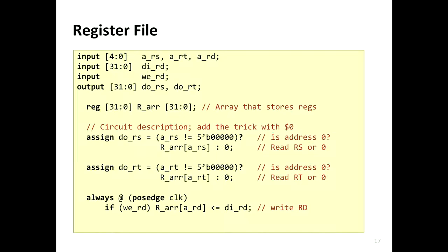And you will actually have some of these files as part of your exercise, and you might have to just implement the ALU. And then you will plug in all these register files that we saw, the memories which we will see in the future. All these things you will plug in Verilog during your lab exercises, and you will see the whole MIPS actually working. So these are all going to be part of your lab exercises as well.